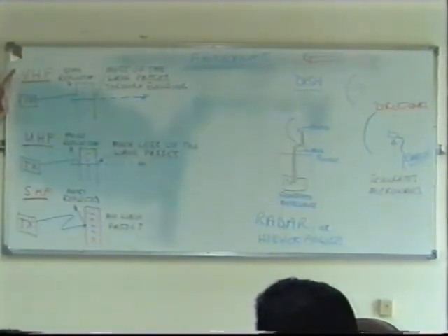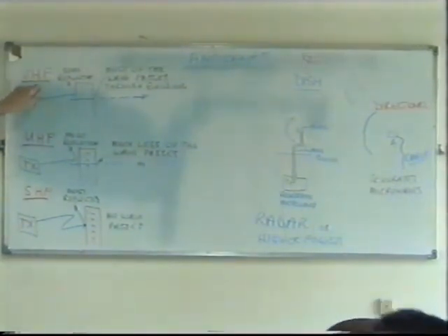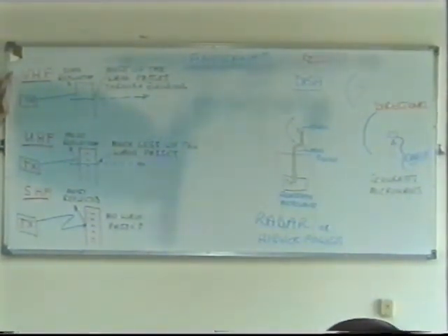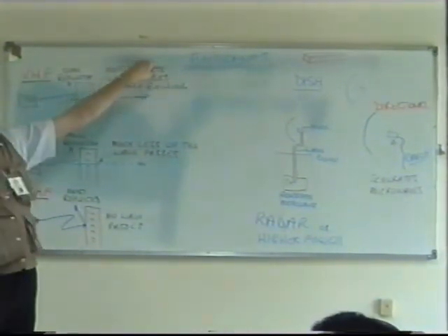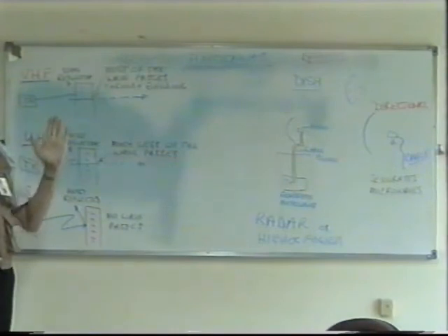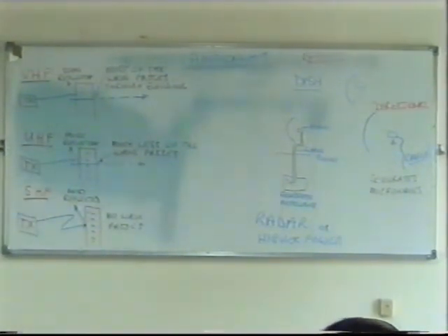You need VHF. UHF is useless for that. I'm not talking about cellular radio here, that's a different story. I'm talking about just mobile communications, private mobile communications. VHF is a very expensive option, but you don't have really much choice. Because remember, the VHF band goes from 30 to 300 megahertz. Well, that only gives me a couple of hundred megahertz or so to play with. And everybody has got to use some channels in there.